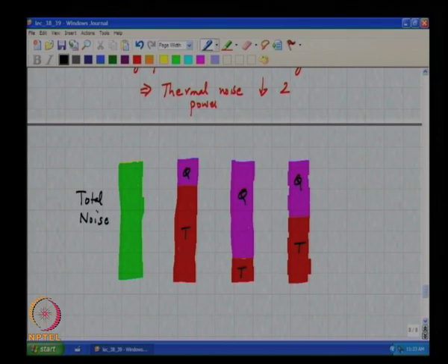I mean, you all understand the question, right? The total noise is so much, and that is derived from the spec of the SNR. You want that to be some level. The question now is, does it make sense to make it all thermal noise or all quantization noise or both of them equal?